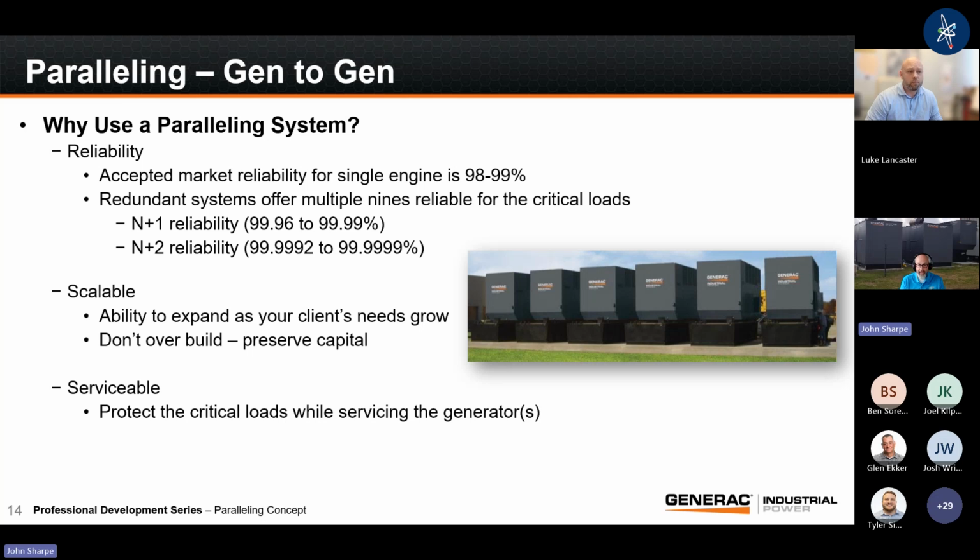If I have 1 single generator and it's down for 4 to 6 hours, I'm not protecting the 10-second loads, or I'm not protecting my data, or I'm not protecting my facility while the oil is being changed. A scalable solution where we're adding generators allows me to maybe shut one generator off, but leave another one online so it is prepared to support the critical loads when I need to.